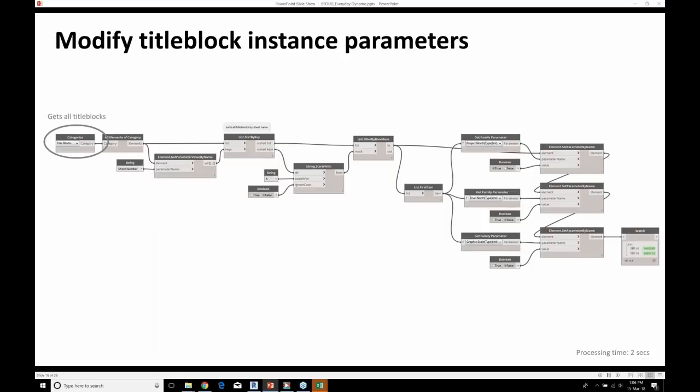So in this scenario, what we're saying is, okay, it returns all the title blocks. It says, let's filter those title blocks based on the sheet number if it begins with, for example, A. So if A is our section or elevation series, then we have a yes or no instance parameter controlling our north point, or project north, true north, and a scale bar options.